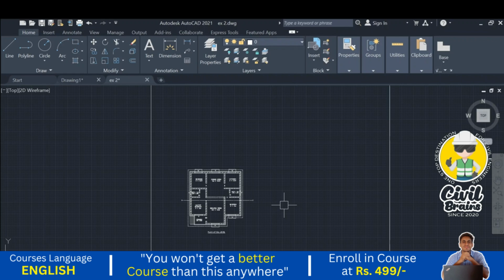After the plan we need to do the elevations. As per the IS standards, the position of the elevation will always be above the plan. Above the plan there is the elevation, and after that, on the right side, we provide the sections, and below the section we can provide the site plan if it is there, or the schedule of openings. In most cases we provide the site plan, then we can provide the schedule of openings, FAR ratios, and all those things.